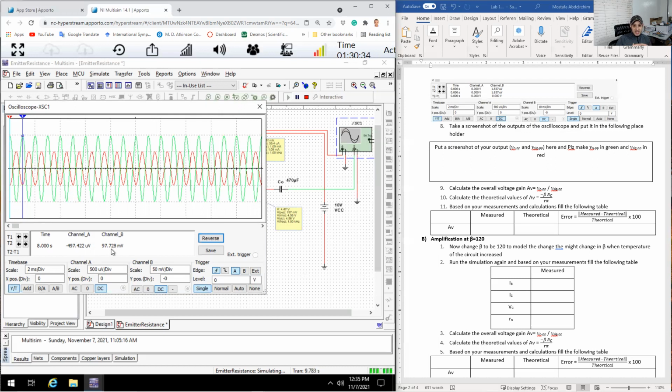When I say 170, that means in the beginning, when beta is 100, you put your effort into the design assuming that beta is 100, and this gave you the required 170. So it's not desirable at all to have something different, because you might use this 170 again in other calculations, in other parts of the circuit. So you want stability all the time.